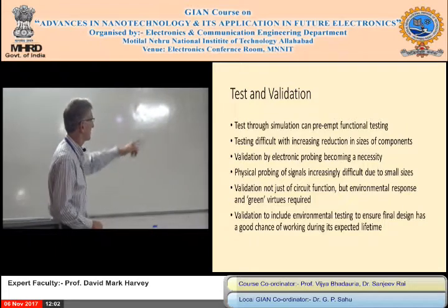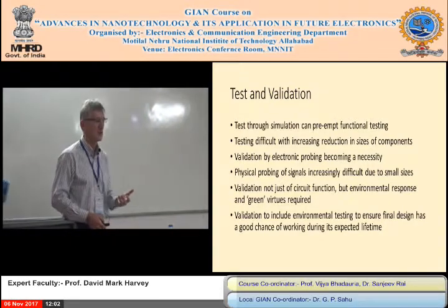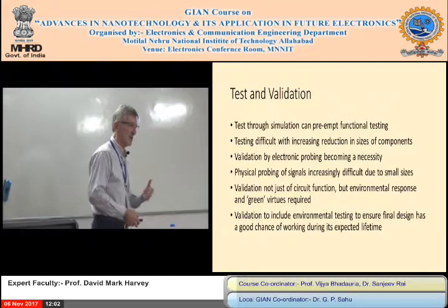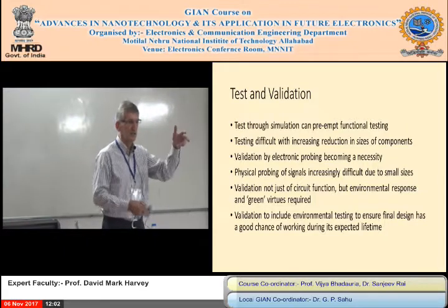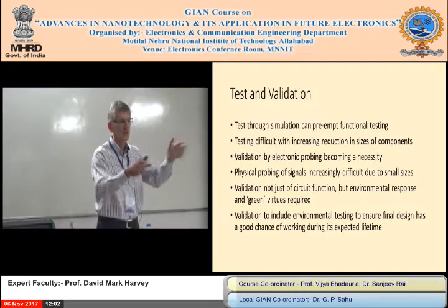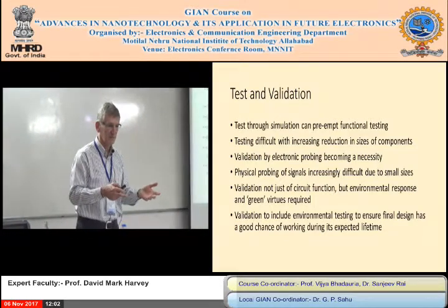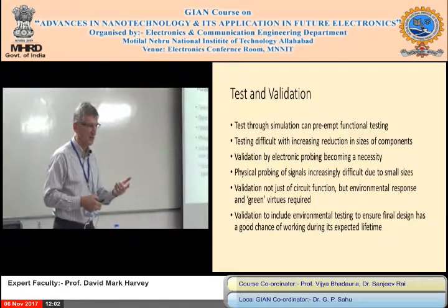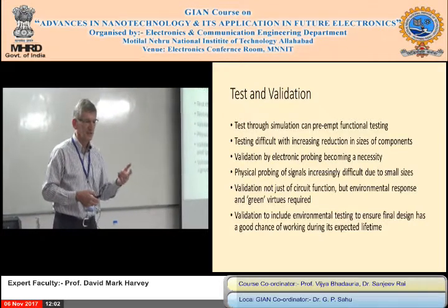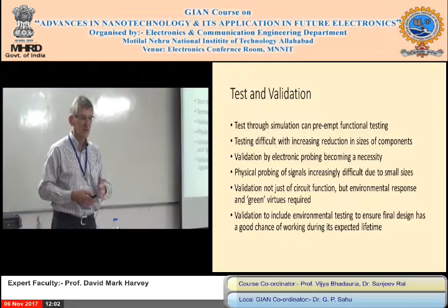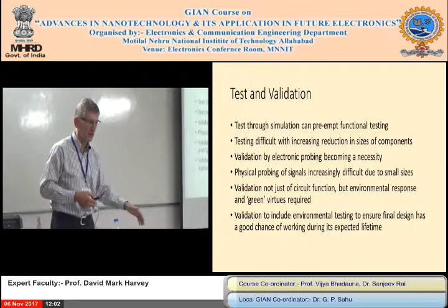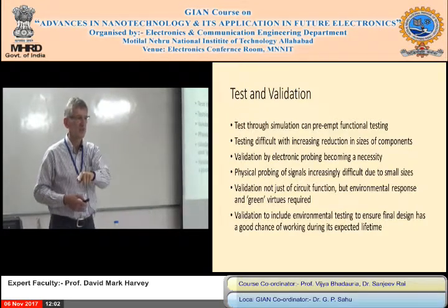So in simulation, you can do some functional testing. Functional testing means how does it work? If it's an AND gate, 2 inputs, 1 output, you put the logic in, you look at the output. It's not just logic. Now we're talking about speed. And you've all learnt about it. I'll do a bit more this afternoon in the lab. All circuits have propagation delay. Going from 1 to 0, you've got a rise time, then a fall time.